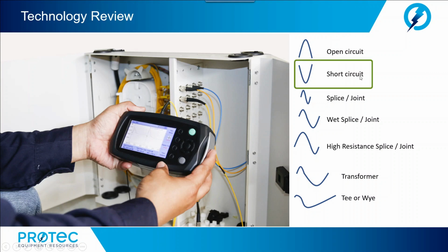In the case of a short circuit, impedance being 0, or the insulation resistance or conductance basically being at 0 resistance, all of the TDR energy reflects back from the short circuit 180 degrees out of phase with the incident energy, or in the form of a negative reflection. Again, the amplitude or depth of the reflection indicates the severity of the event.